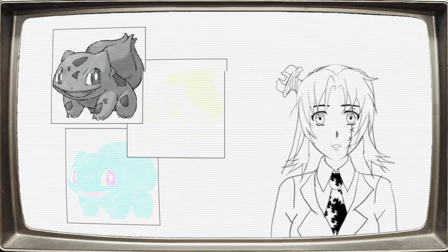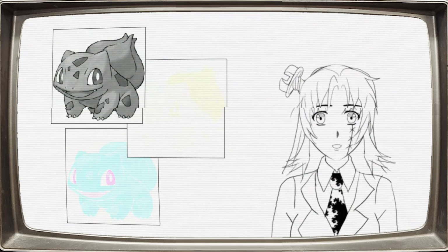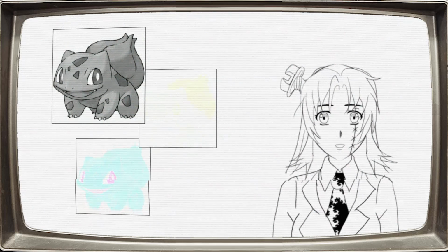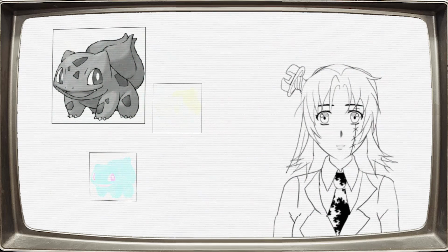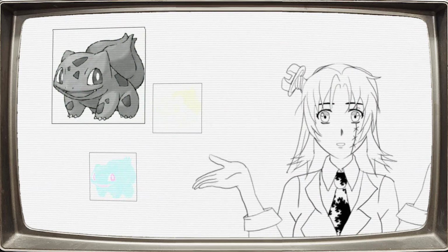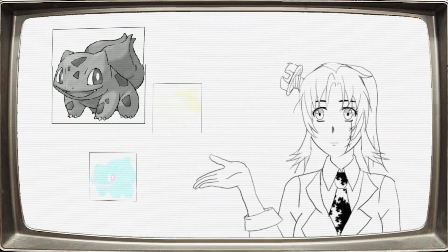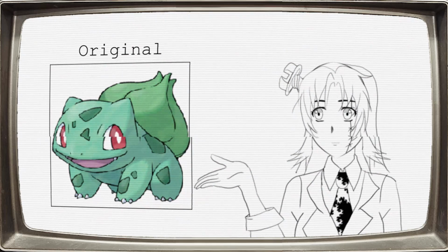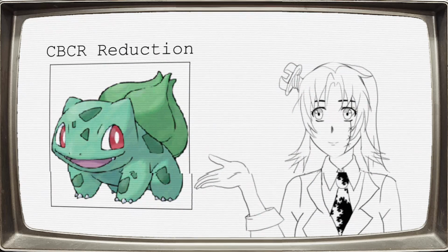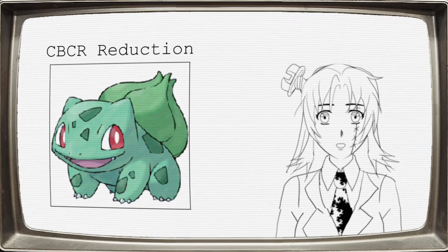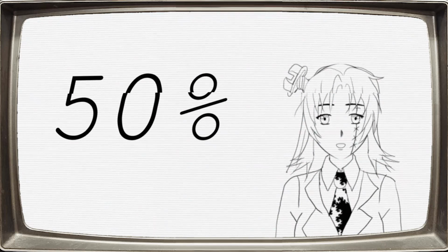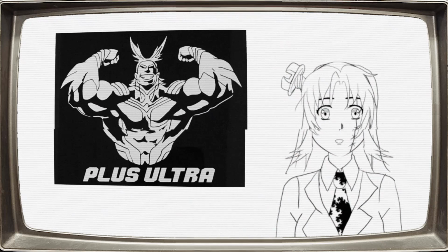Since our eyes are way more sensitive to brightness, we'll leave the luma channel unchanged, but we'll cut the resolution of the Cb and Cr channels both by 75%. This may seem like a drastic change, but the effect is barely noticeable to our eyes. This is the original image, and this is the image after the reduction of the Cb and Cr channels. You'll need to look really hard to actually spot the difference. So, with this simple trick, we already achieved a 50% compression rate with almost no perceivable loss in quality. But we can go even further than this.